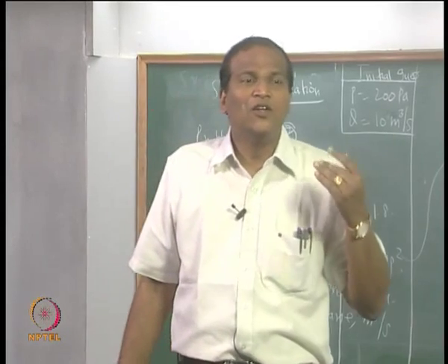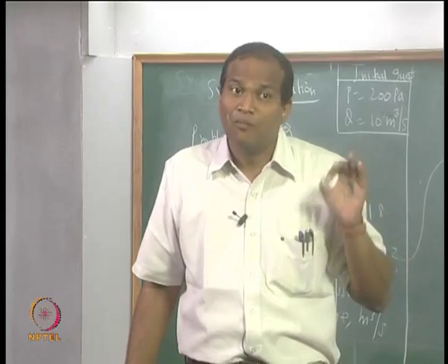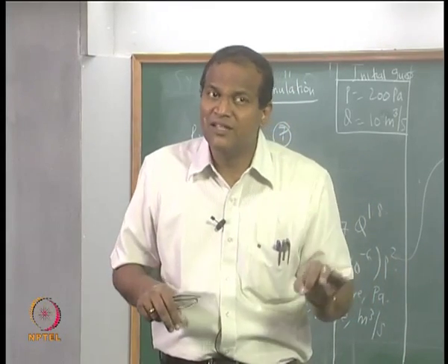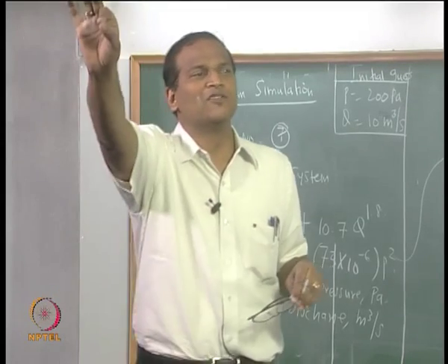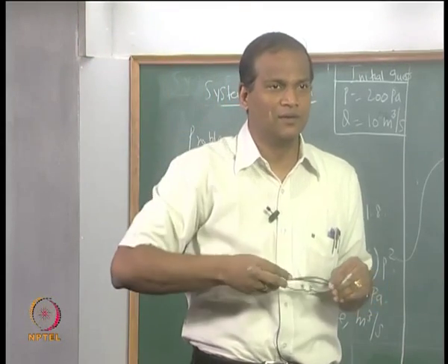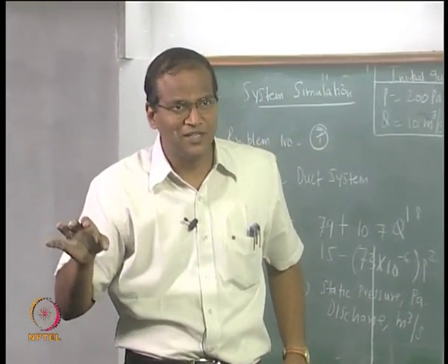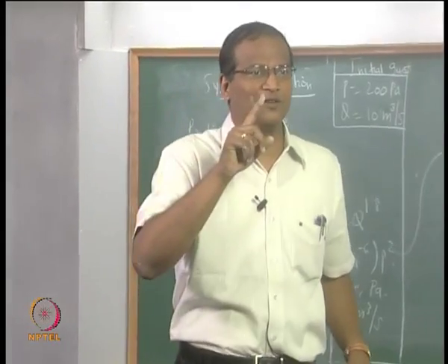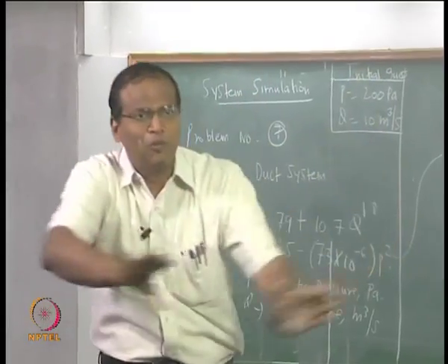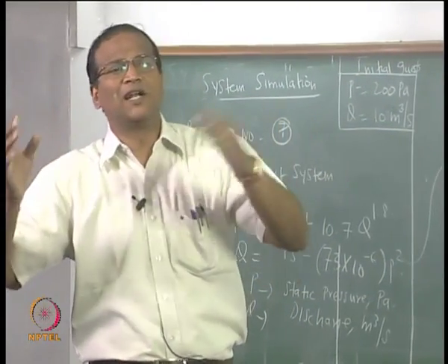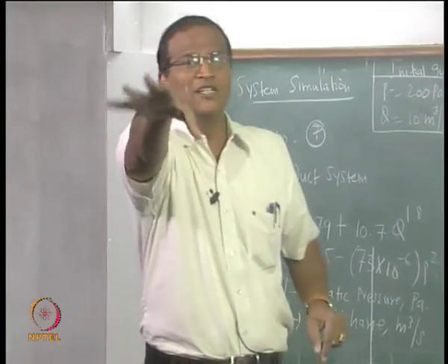So you are always looking at the difference between successive iterations, but this can mislead you, because it is possible for you to converge beautifully to a totally wrong answer. Once you have reached convergence, it does not necessarily mean that you have got an accurate solution. Convergence means that with the present numerical scheme, if you proceed for 100 more iterations, you cannot expect a significant change in the answer, but whether that answer itself is correct or not, convergence will not tell you.